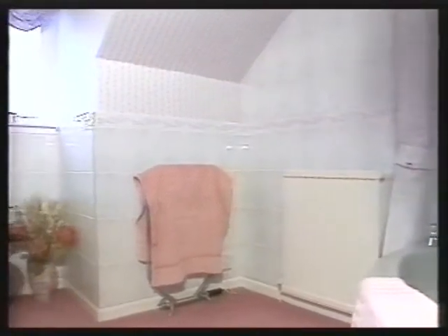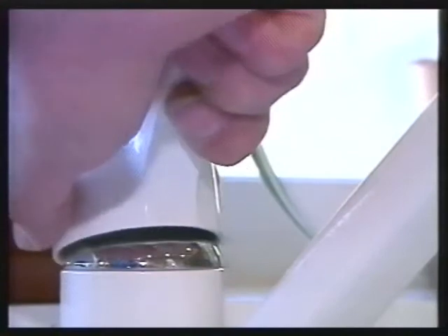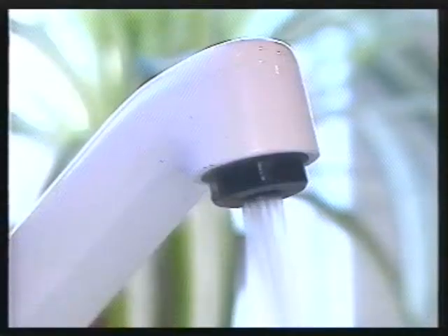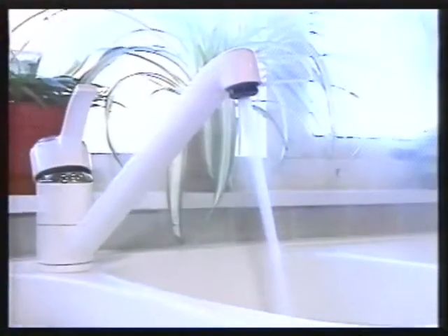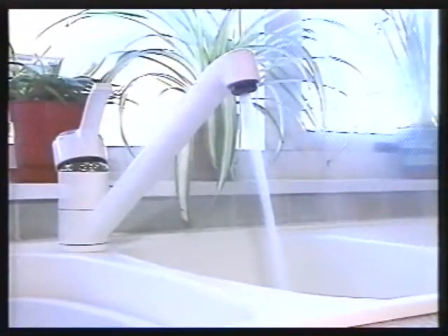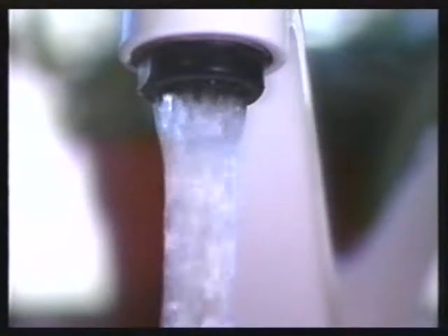Now do the same for all the other rooms and spaces, and add it all together to get the total heat emitter requirement. Remember to add an allowance for domestic hot water. Then choose a boiler with an output as close as possible to this. Again, make sure the output's not less than the figure you've worked out.